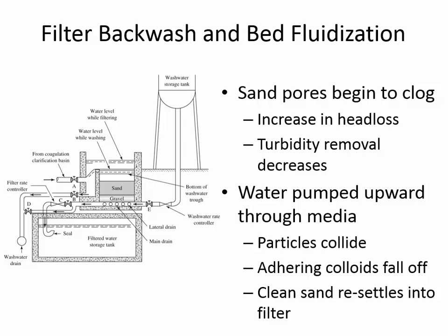Yeah, they'll do that, except you have to separate it somehow, because if you took all of the backwash, including the particles, then it would be like a loop, and the particles never get out. There has to be some way to take the particles out, or else there's an accumulation. Sometimes they'll try and concentrate the backwash through vacuuming out the water, or they'll put a sludge through a filter press and squeeze the particles so that the water can be recycled, but we can't send the whole stream to the very front. Otherwise the particles would accumulate.